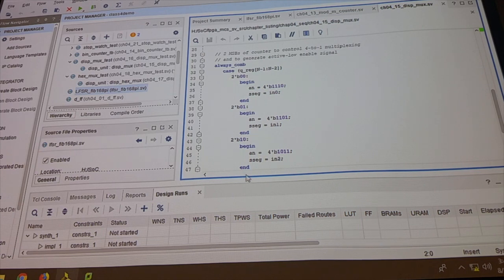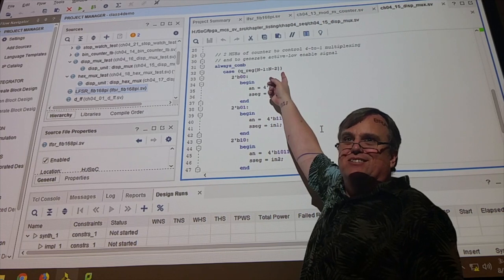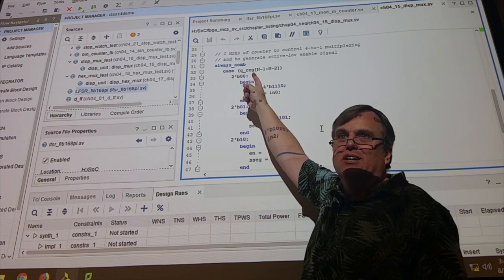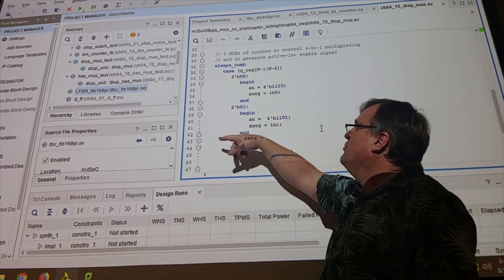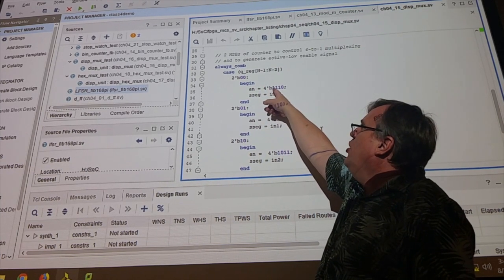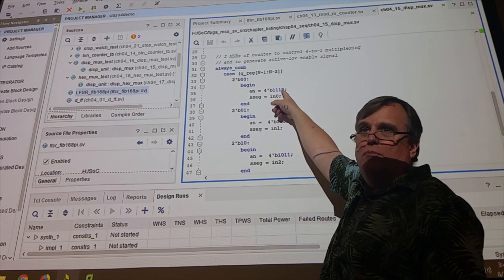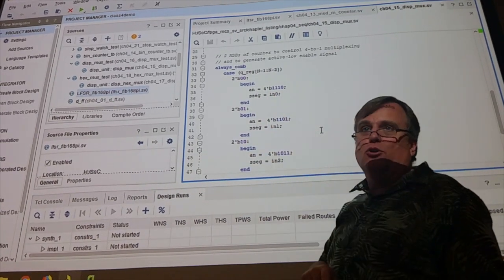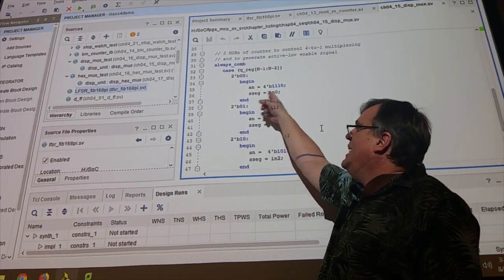So what's going on with this? It's letting the display sequentially. He's taking, remember I told you the last two bits? So n is the number of bits, so the high two bits are n minus 1 and n minus 2. He's taking the high two bits, and if there's 0, 0, then the anodes, the first three are off, the very rightmost one is on, and whatever you said the pattern was for the 7-segment display, it writes that to the 7-segment display.